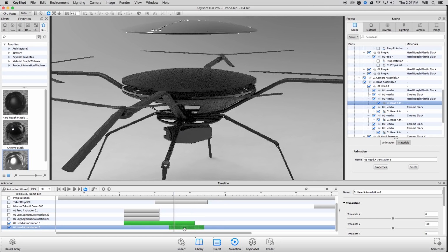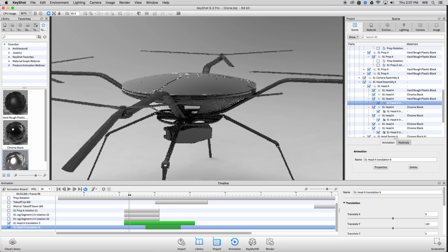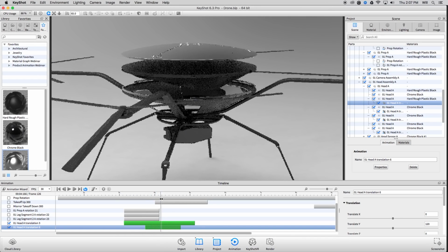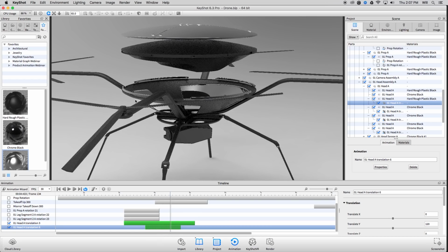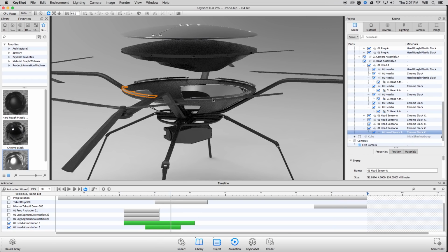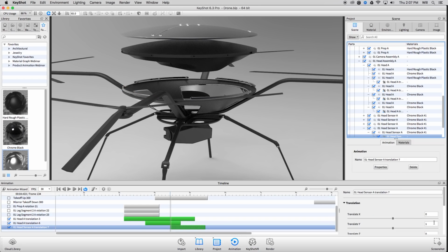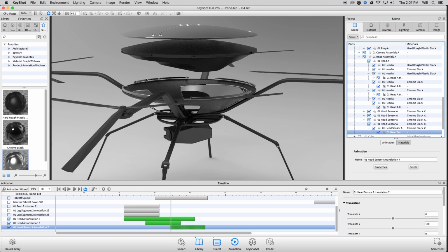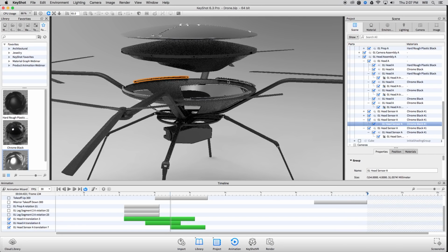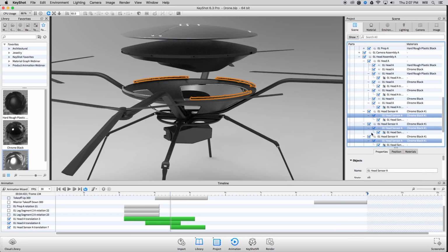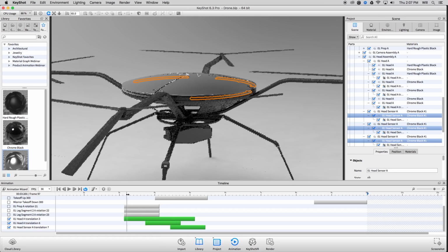Or, well, that's the thing. We can move it so it moves at the same time, or we can have it delay a little bit. So first off, those 3 plates move up together, then the next piece comes up, and then maybe I want those 3 parts underneath it to move together. So I can do one more, translate this piece in the same direction, maybe just 100 millimeters, and then copy that animation and apply it to the following parts. I can multi-select those just like usual. Right-click those in the scene tree, paste linked animation, and those should follow the other 2 pieces.